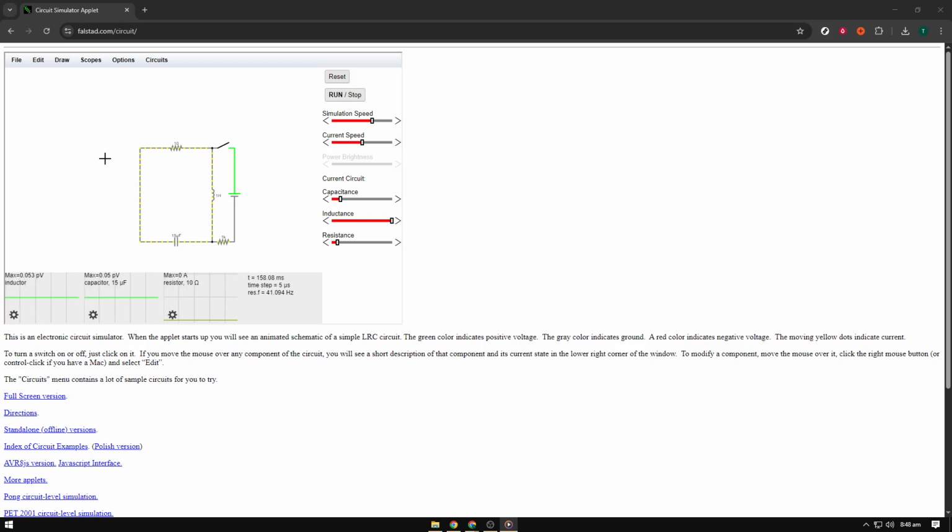Start by selecting the components and wires you want to copy. The easiest way to do this is to click in an open area and drag a box around everything you want to include. As you draw the box, make sure all relevant parts are fully enclosed, including the connecting wires and any small junctions. If something isn't highlighted, it won't be duplicated.